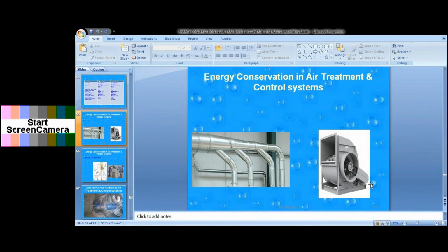So because of that, more dynamic pressure will be there. So that got reduced, as well as for the required air volume, if you select the correct duct, then your pressure drop is less. So we redesigned that, and totally it has saved. And also the bends, wherever possible, instead of 90-degree bends, we changed the layout to the shortest distance.